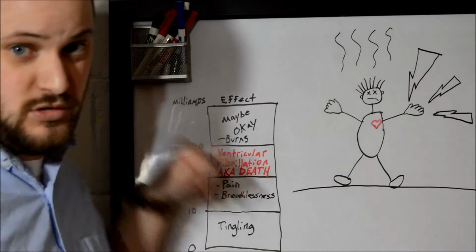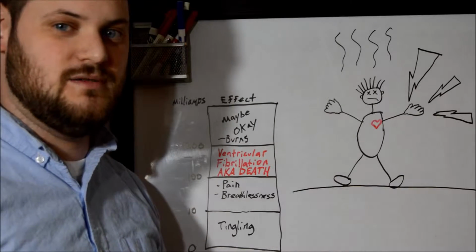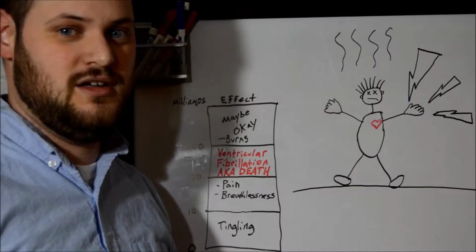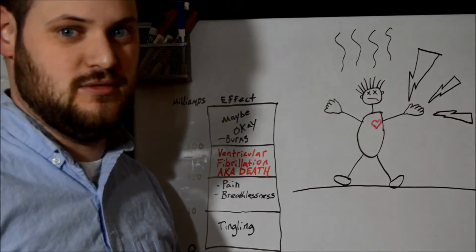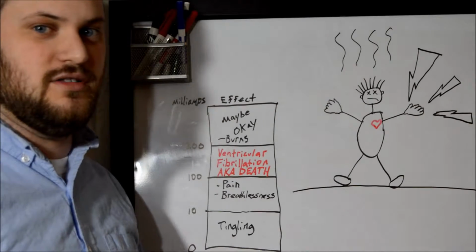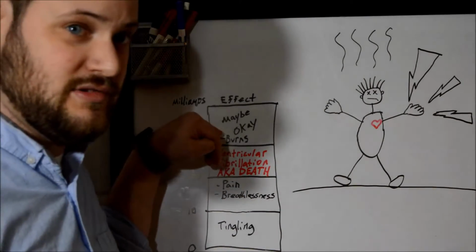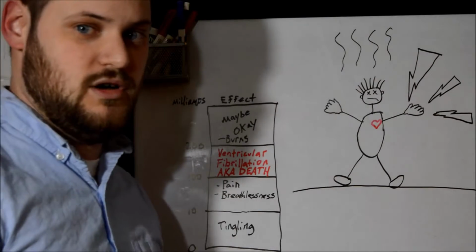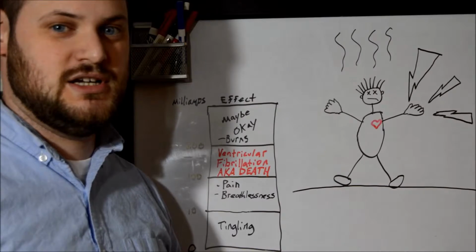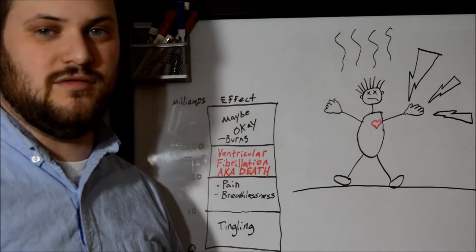Yeah, your heart could potentially stop, but it's been found through studies that you can actually have a better chance of restarting the heart with chest compressions and breathing, because there's not as much damage done to the actual heart itself. Although, as you get up into these high current levels, you're more prone to burns. You could have more tissue damage, could have brain damage. Any of your soft tissues are at risk.